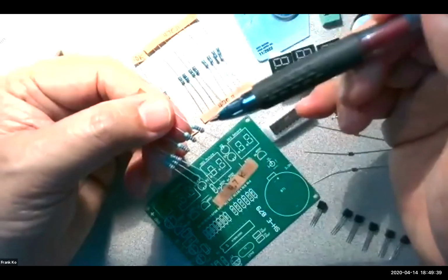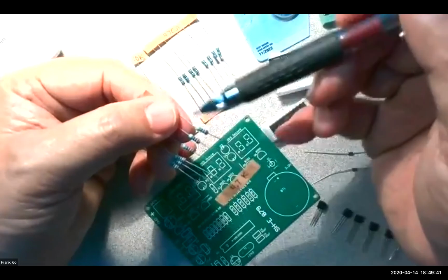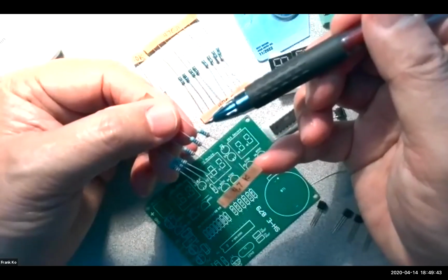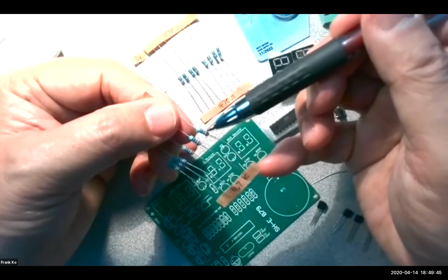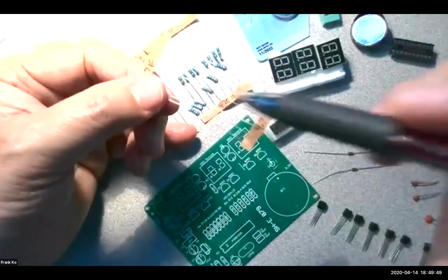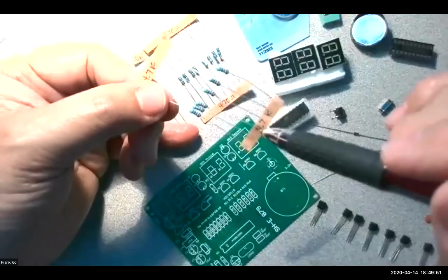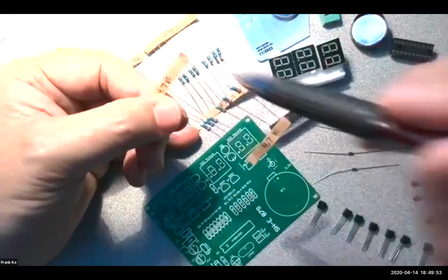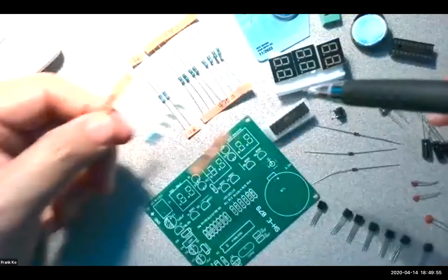So these are precision resistors, excellent resistors. Again, the color coding is yellow, violet, black, brown, brown. You should account for 6 of those, and when you have 6, mark them 4.7 on the little masking tape and set them aside.